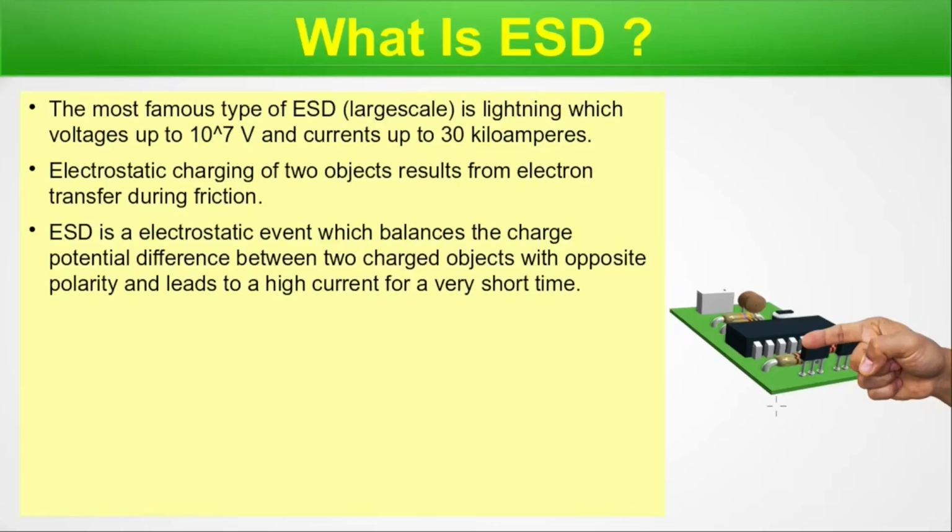Those electronic engineers who do this kind of assembling and handling of circuits use an electrostatic strap that they tie to their hand and which is connected to the ground, maybe with two different ESD straps in both hands, so that the human body is electrostatically protected and touching any device will not damage it. Such electrostatic straps are used in the electronic industry where electronic circuits are packaged and assembled. This is just for your knowledge.